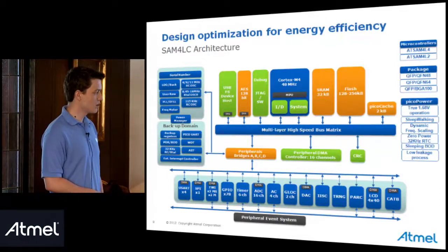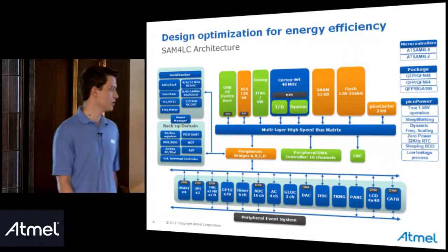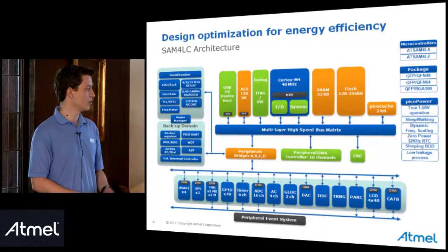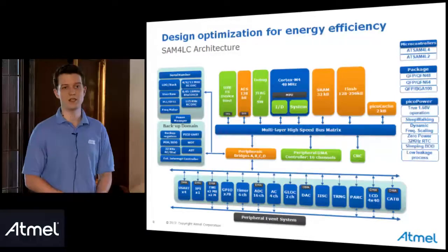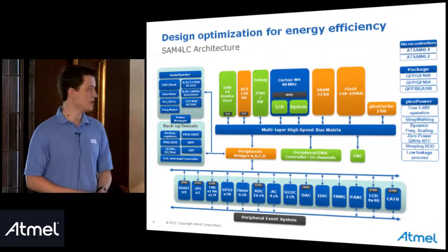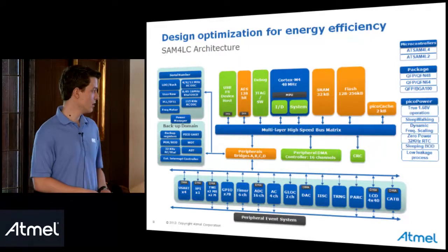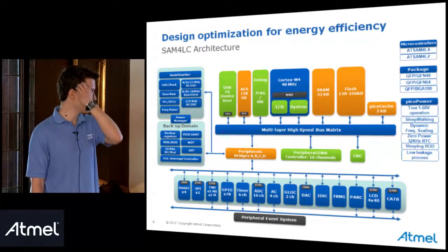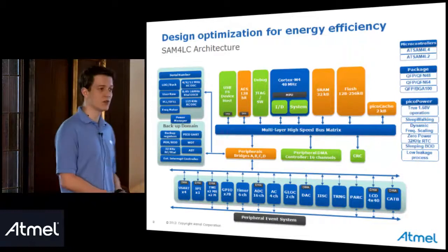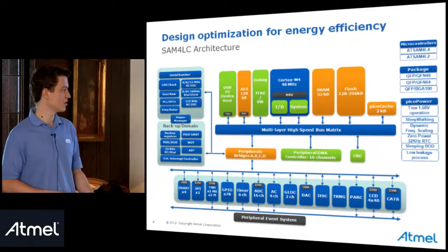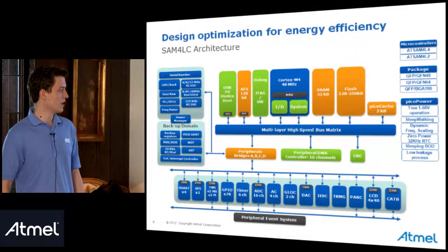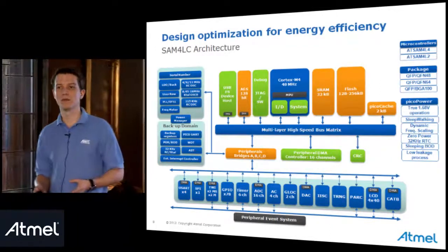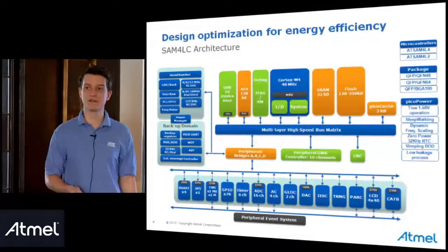Then concerning standard peripherals, we have all the communication peripherals, such as 4 UART, 1 SPI, up to 4 TWI. TWI stands for two-wire interface, so it's I2C. Up to 78 GPIO, 6 timers, 1 ADC, 1 analog comparator, a glue logic. We'll see after what the glue logic is, a DAC, and then the other part of the peripherals is what we call application-specific peripherals.